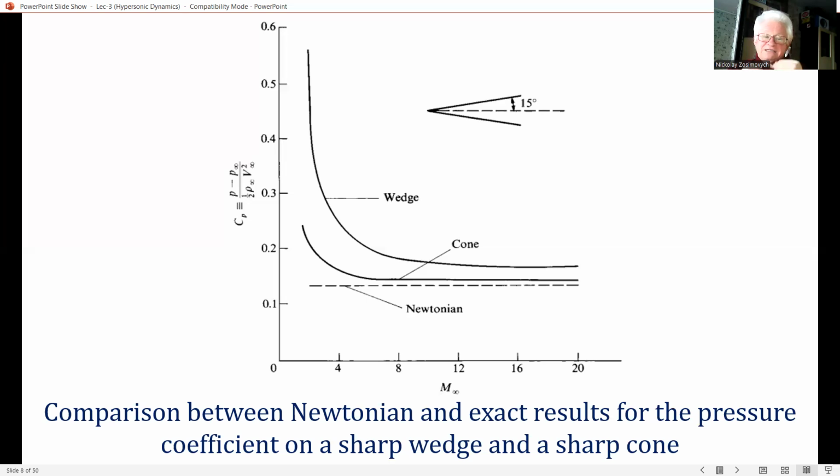Furthermore, we are tempted to say that Newtonian results for blunt bodies should use the modified Newtonian formula, and that such results usually produce acceptable accuracy as illustrated in the previous figure. In contrast, we suggest that Newtonian results for slender bodies should use the straight Newtonian law.